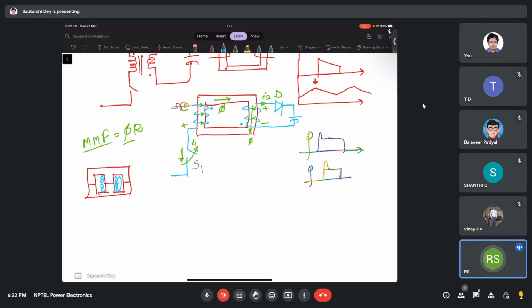No, sir, my question is whether the leakage flux is proportional to the permeability of the copper wire or the permeability of the air. That's what I'm saying. The permeability of copper and the permeability of air, there is not much difference. Copper is also, what is that called, diamagnetic, no? But it is not magnetic. So it is as good as air in terms of relative permeability. I think the mu of copper will be very close to 1. It will be, right?